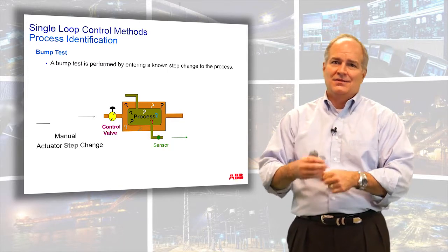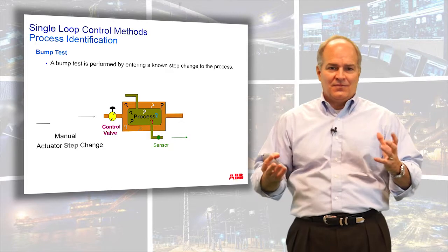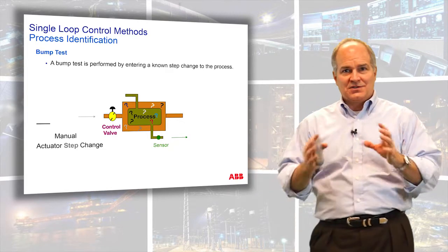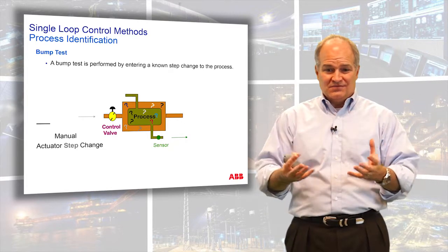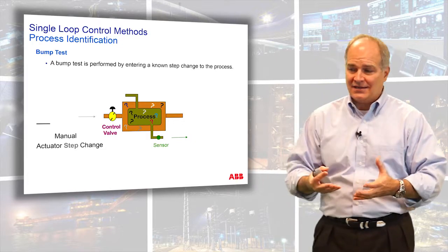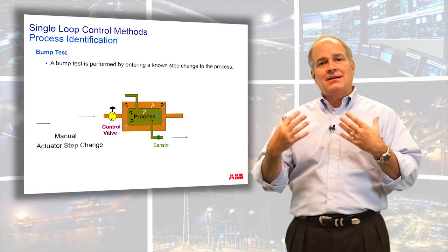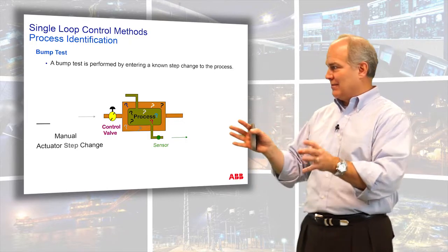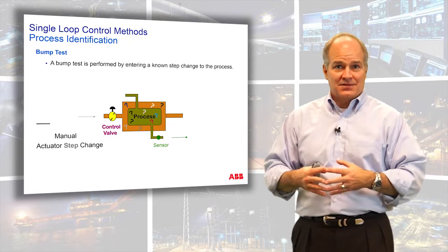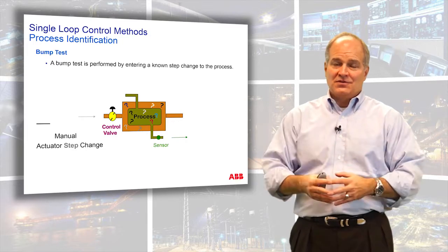Look at the packing material. I've seen valve positioners that are open and full of dirt. I've seen cases where they've gotten water in their airflow and they've got rust. You need to take a minute. Don't just think you can fix everything through software and these nice operator displays. Sometimes you need to do a visual inspection.